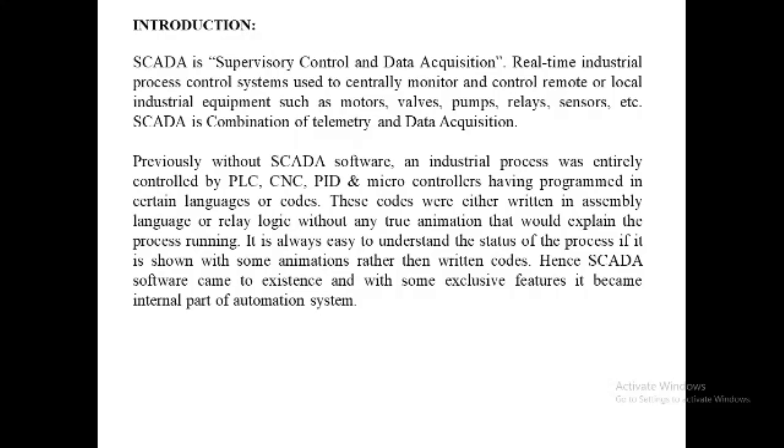Let us take one example. In a SCADA system, a PLC can be used to control the flow of cooling water as part of an industrial process. At the same time, the supervisor can use the host control function to set the temperature for the flow of water. It can also have alarms and can record the water temperature and report back.